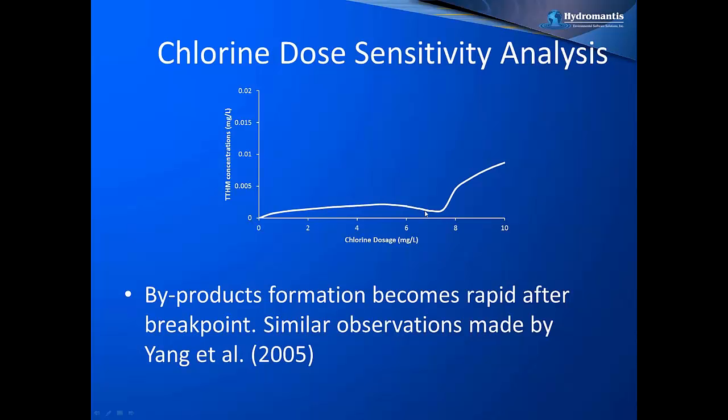There are a significant number of studies that have been done by Yang et al. on breakpoint chlorination and how the total trihalomethane concentrations change in the system, and these kinds of curves are pretty similar to the observations that have been made by this particular author here.